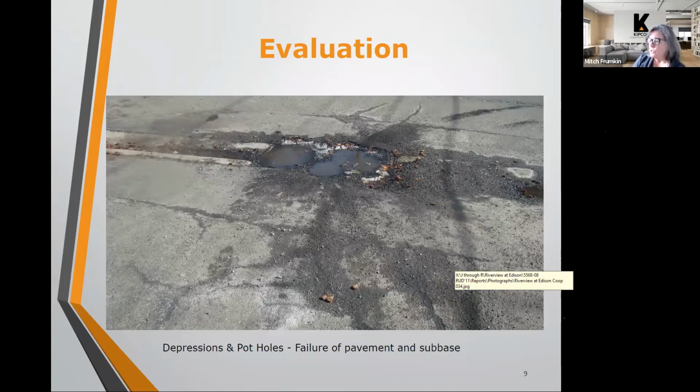But once the pavement reaches a certain age and a certain level of deterioration, spending money on maintenance just becomes a losing battle. You start spending more and more money on maintenance, and you have to look at how much you're spending on maintenance versus how much of that maintenance cost would be alleviated if you went ahead and remediated the pavement, because a lot of those maintenance issues that recur over and over and become expensive go away when you have a newer pavement.